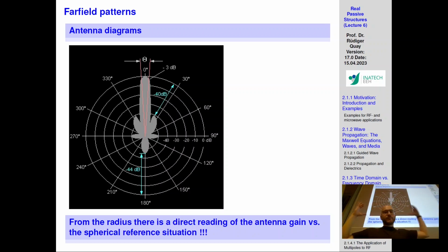The 2D plot here, what does it say? Well, in the radial axis, you have the definition of the angles. So how wide your beam is, your 3 dB beam width. Your main beam is where your antenna focuses most of your radiation. Obviously, there's going to be other radiation that goes beyond your main beam. How wide this beam is, that's the 3 dB beam width. It's also very important to know at what point the radiated power drops by 50%, by half.